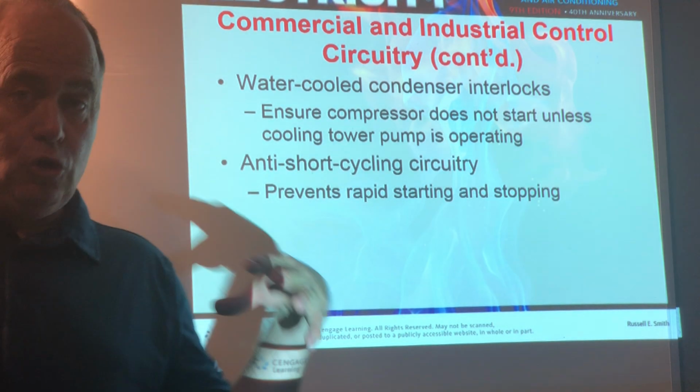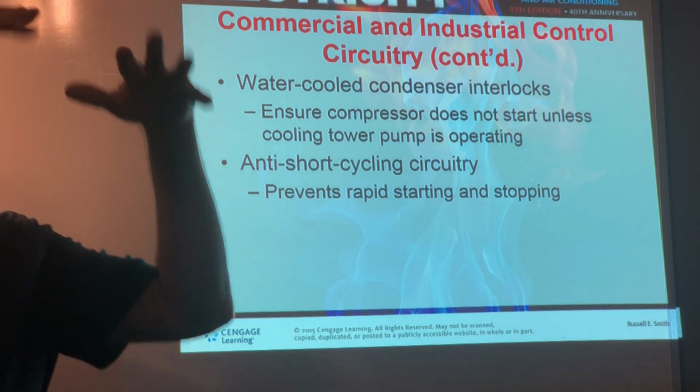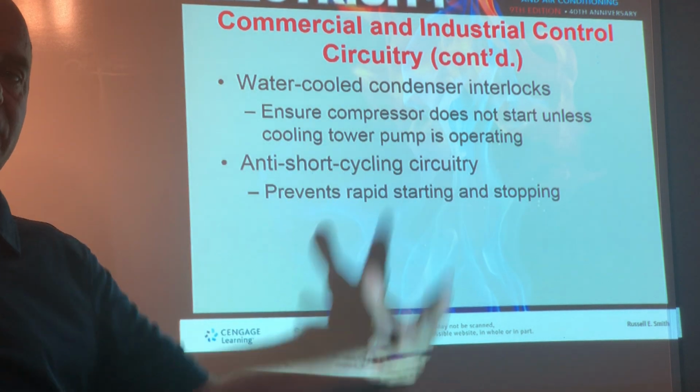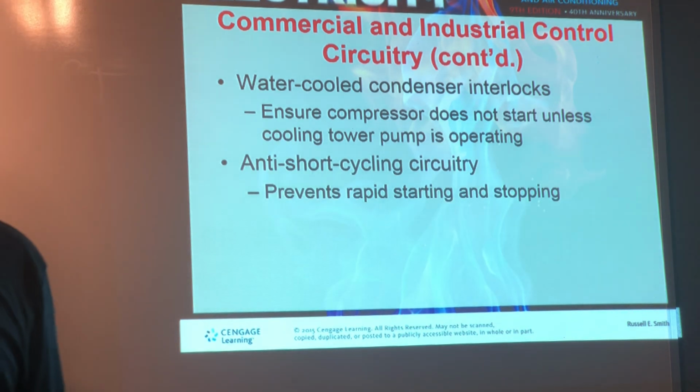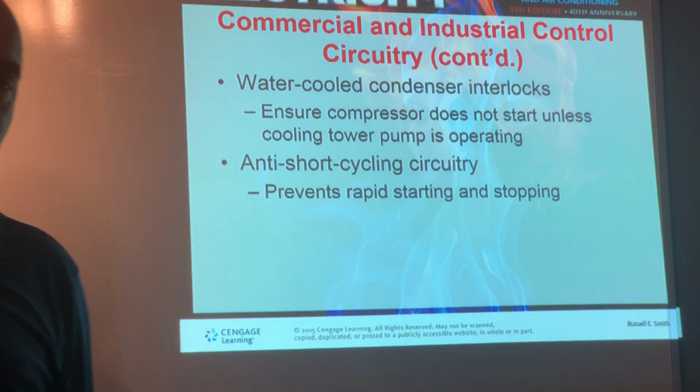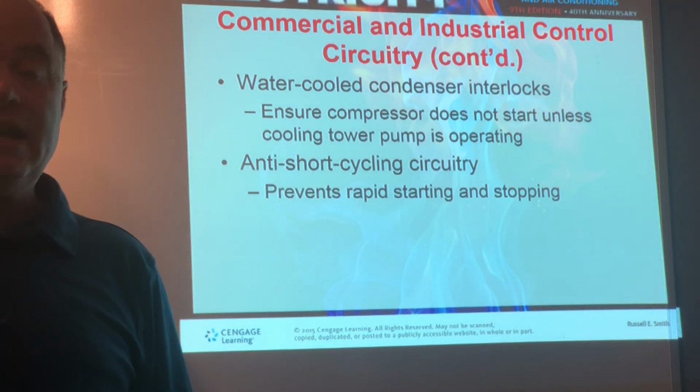These are generally going to have a cooling tower where water trickles down and evaporates, and through that evaporation process primarily we get rid of the heat of the building. And the water-cooled condensers can be very small, and you might have many of them.